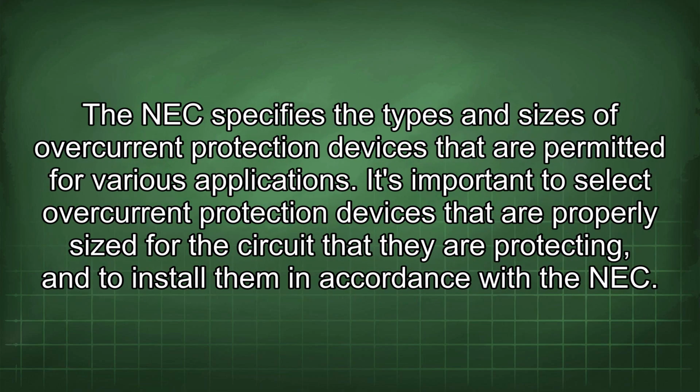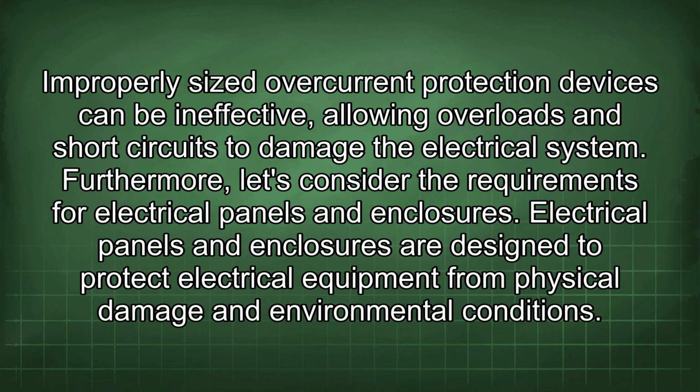The NEC specifies the types and sizes of overcurrent protection devices that are permitted for various applications. It's important to select overcurrent protection devices that are properly sized for the circuit that they are protecting, and to install them in accordance with the NEC. Improperly sized overcurrent protection devices can be ineffective, allowing overloads and short circuits to damage the electrical system.